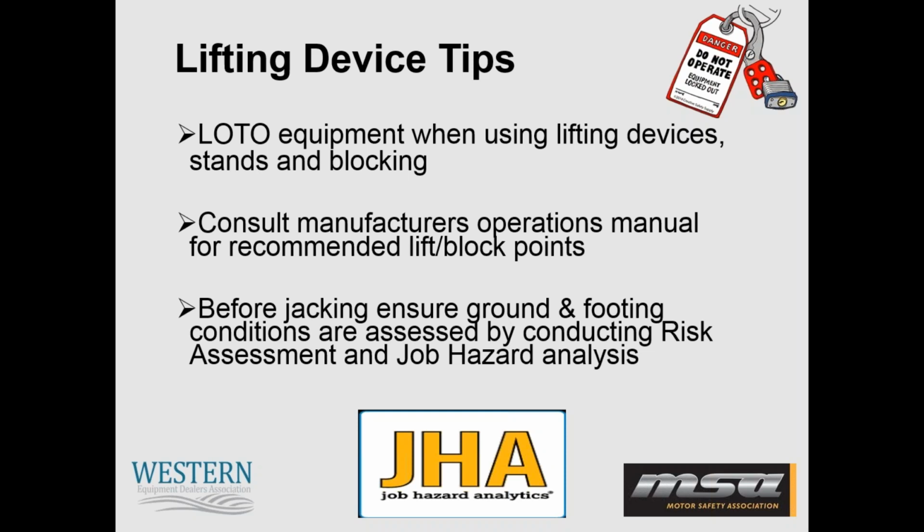And again, another device tip would be to consult your manufacturer's operation manual. There could be different lifting or blocking points indicated in the manual. Some of the manufacturers have gotten a lot better at providing the dealers with information on where I can put my jack or where I can block the piece of equipment.